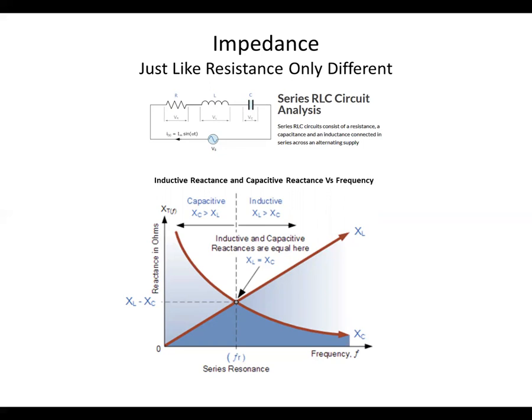And we'll get into antennas and explain why. So what we can do is adjust the length of the dipoles to move this resonant point to where we want it to be most effective in the band that we're transmitting. We'll come back to this when we get into antennas. But something I hear a lot is people talking about adjusting their antennas.